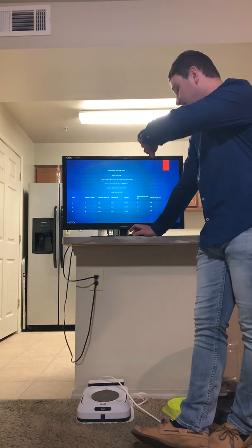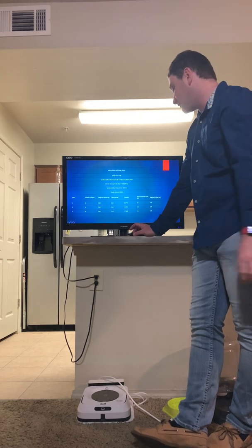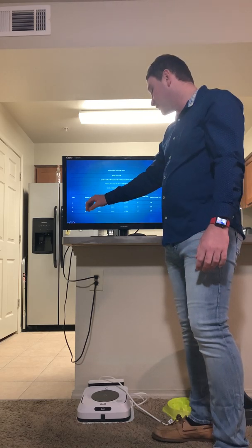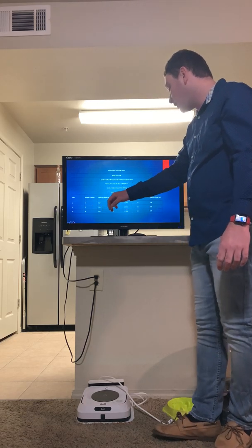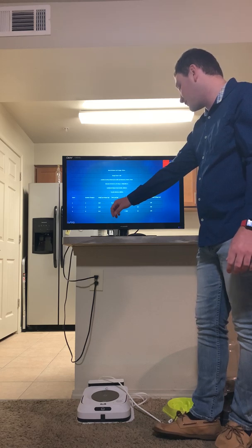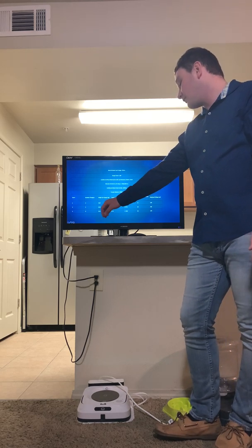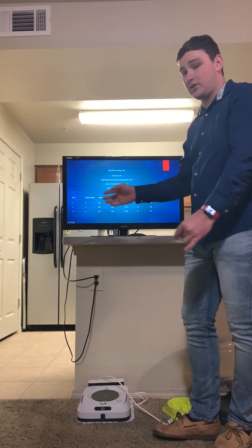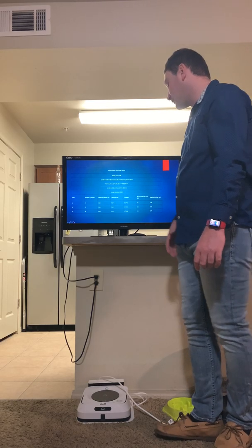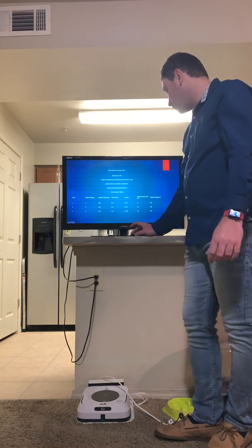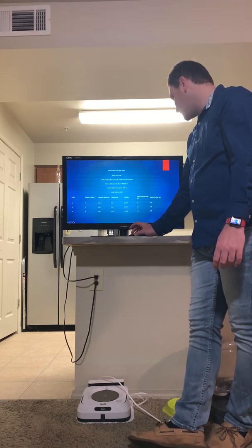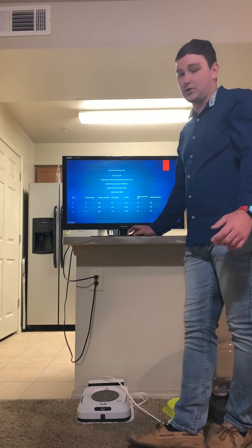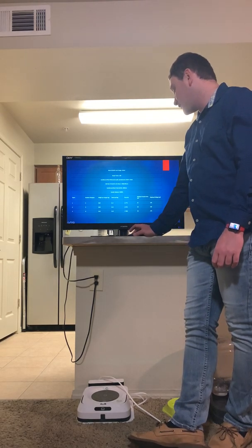So this is the table to explain some of the data that we had. We did 3 different tests with, like I said, 4, 5, and 6 hangers. Each hanger was 0.3 kilograms, but it was just a matter of where we added it. We added it consecutively along the cantilever beam in certain dimensions. So we have the weight per hanger, the total load, the force, and the displayed tensile strain, as well as the displayed voltage as recorded from the Wheatstone bridge display device. So on to the next slide.